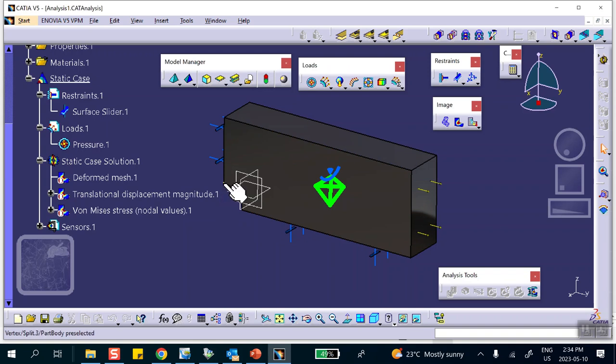If there is a big change, chances are that neither one of those are reliable. Not chances, neither one of them are. Make it smaller, and then repeat until things don't change that much. Okay, this is what a mesh convergence study is.